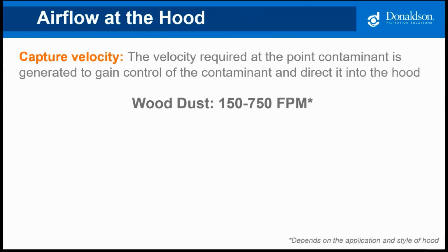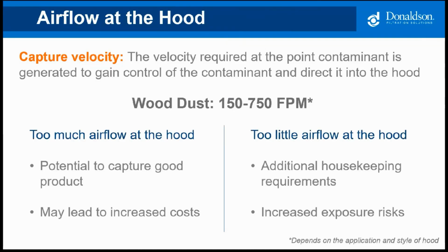So when you're designing hoods, we want to avoid airflow extremes. Too much airflow at the hood or pickup point may mean you're picking up good product rather than just nuisance dust. It also can increase your risk of capturing unwanted particulate like sparks or embers. And since more energy is required to move more airflow, it could lead to higher than expected operational cost. Insufficient airflow at the hood could require additional housekeeping measures to be implemented. Depending on the dust, it may lead to increased risk of exposure.